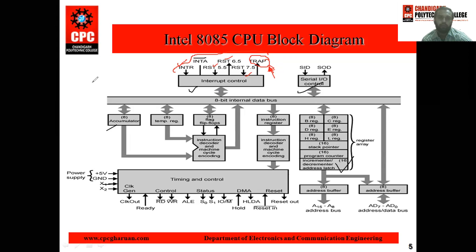If we want to perform any arithmetic and logic operation, then at least one operand is stored in the accumulator, and the second operand can be stored in registers, an address, or anywhere else. We can apply the command on the accumulator and registers, and the result is stored in the accumulator by default.